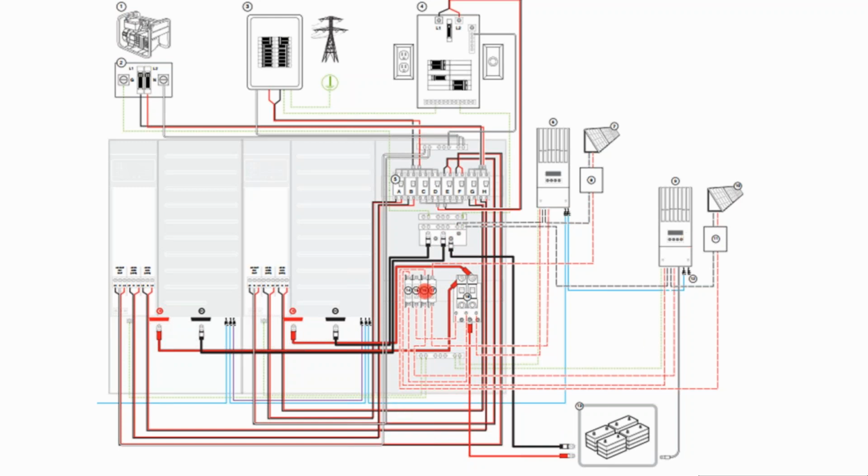Here are our charge controllers landing on breakers that then get wired to our DC bus. And so we see our charge controllers on breakers, our inverter going to the inverter. That's that disconnect switch breaker. And then we have an AC side on top. Multiple charge controllers, one battery bank.